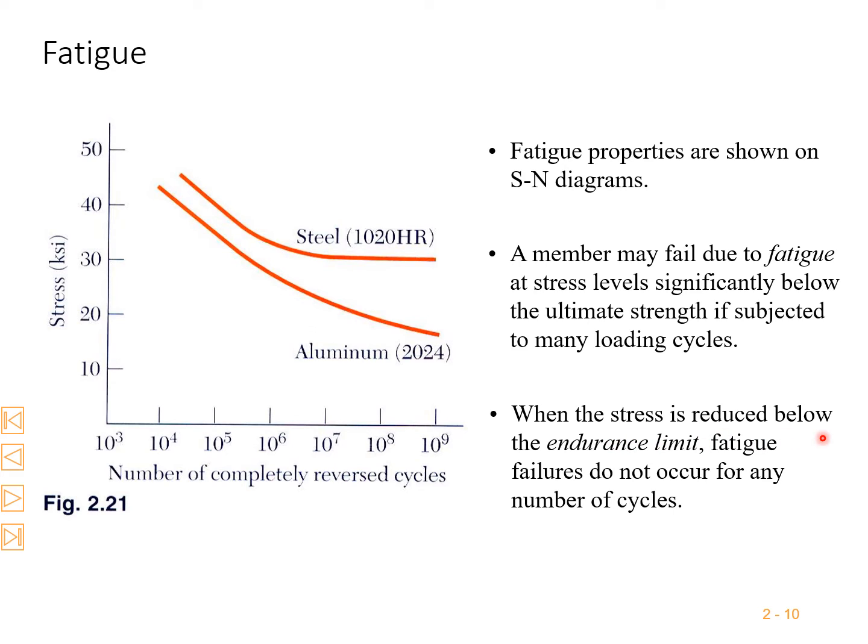When the stress is reduced below the endurance limit, the fatigue failures do not occur for any number of cycles. That means if you apply less number of cycles, it's below the endurance limit, so it does not have any impact on the stress values.